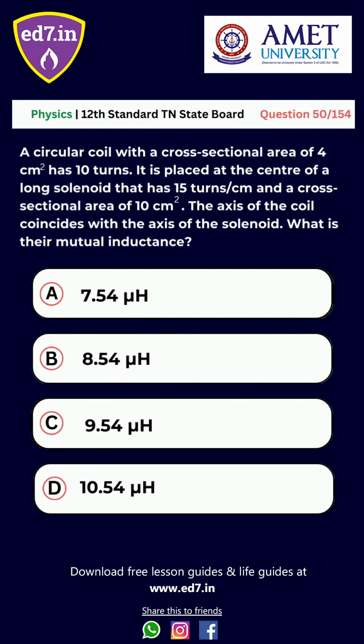Question number 50. A circular coil with a cross-sectional area of 4 cm² has 10 turns. It is placed at the center of a long solenoid that has 15 turns per centimeter and a cross-sectional area of 10 cm². The axis of the coil coincides with the axis of the solenoid. What is their mutual inductance? Option A 7.54 μH, B 8.54 μH, C 9.54 μH, D 10.54 μH. Right answer is option A, 7.54 μH.